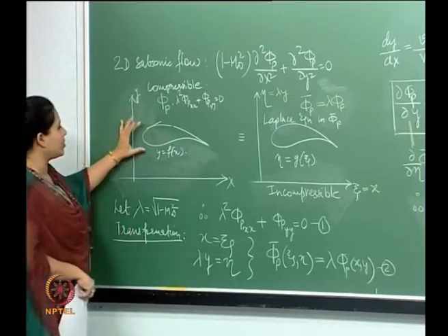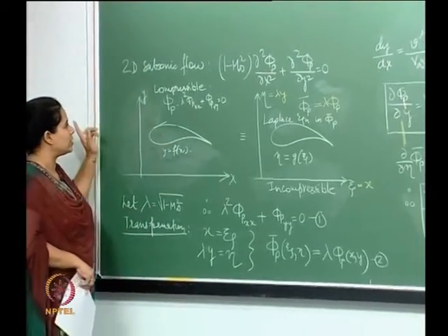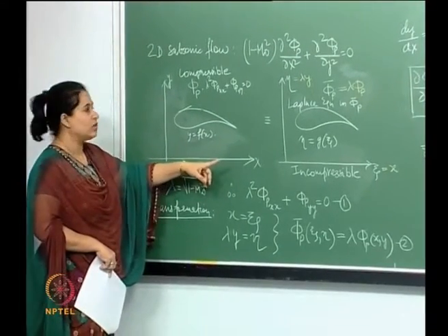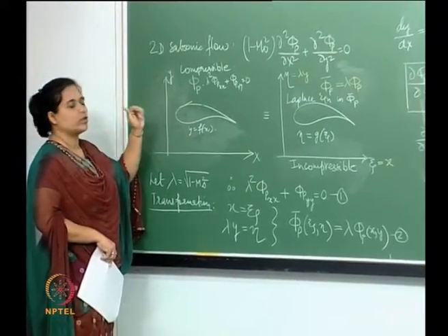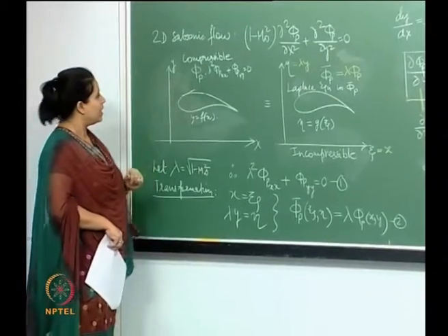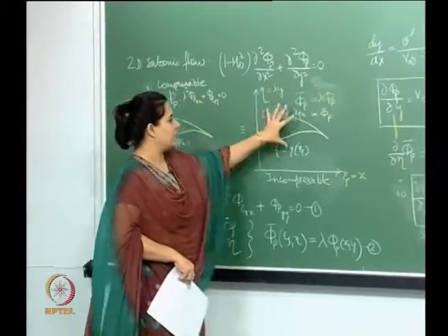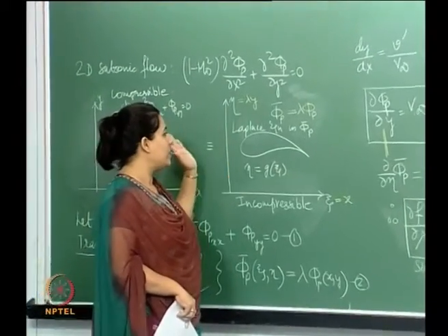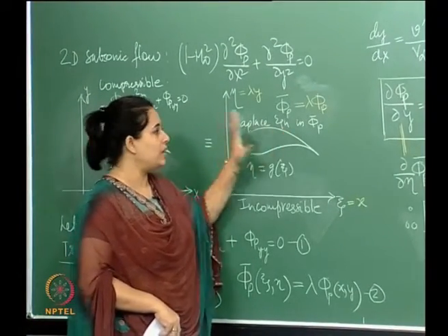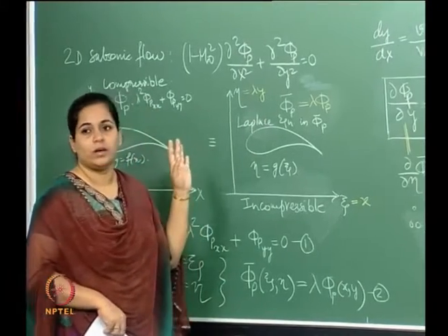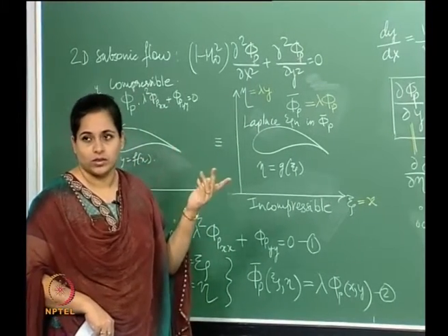Meaning, say we have this particular body, in one case we consider a compressible flow over it. So, we get a coefficient of pressure which is Cp. Now, consider another case where we have the same body and an incompressible flow over it, and the corresponding pressure coefficient is Cp naught, right.